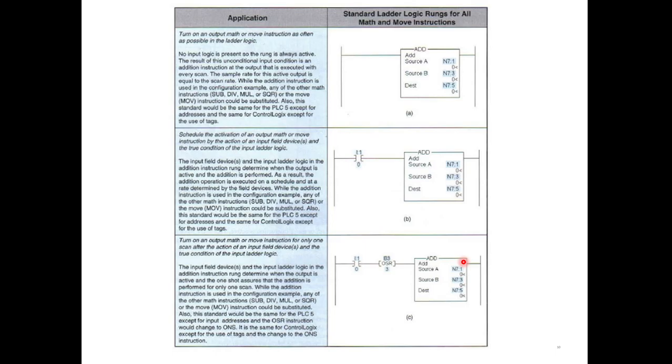Okay. Now, these three additions, what do they mean? The first one means that once you power on the PLC, it will do the addition. It will not wait for any instruction. And this second one means if you power on and if you press this button, as soon as this rung is true, it will keep on adding.